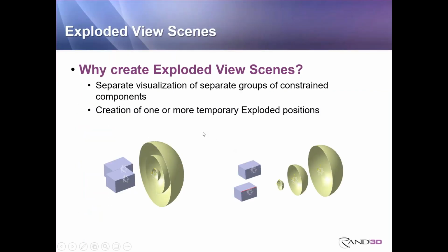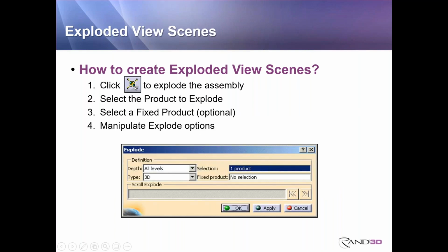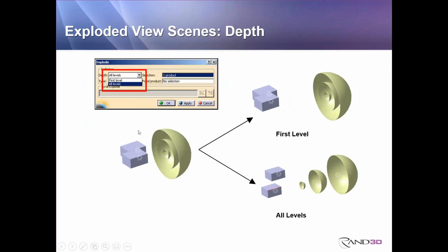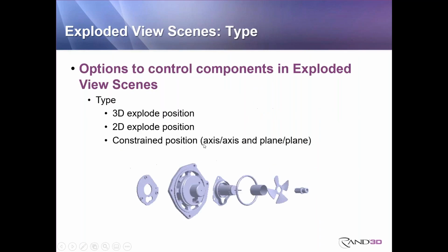Exploded scenes, I kind of got into this already, but we have the ability to either manually explode or use the explode command to show them in different configurations. Again, selecting explode will bring up the dialog box. We'll be able to define depth at all levels or at the first level. We'll be able to define them whether it's 3D, 2D, or constraint based.